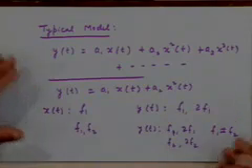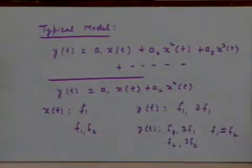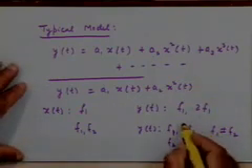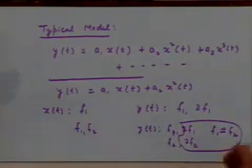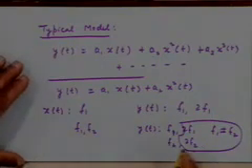Right? You can see that. It's a matter of just writing down the trigonometry and seeing that you will get terms which is cosine of 2 pi into f1 plus f2 times t and 2 pi f1 minus f2 times t. So these additional frequency components that are getting generated is the real problem in nonlinear distortion, right?